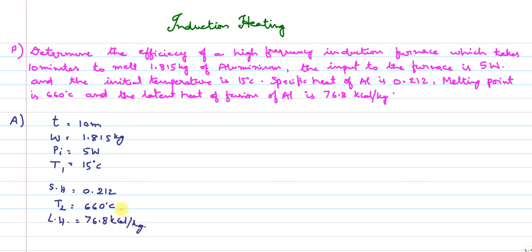Now we need to find out the efficiency of the induction furnace. We know that efficiency is equal to output power divided by input power. We know the input power but we don't know the output power, so we need to find the output power. How to find the output power? Before that, we need to find the heat required by this induction furnace.